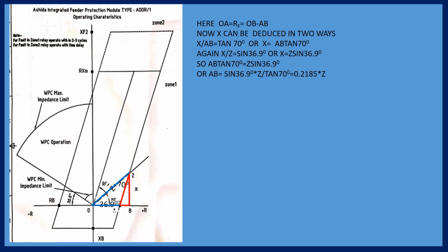In the DC test, you have to find out the polarity for CT S1 and S2. So in the previous slide, I have told you how to connect the CT secondary. It will be in series connection, because current is flowing in series.